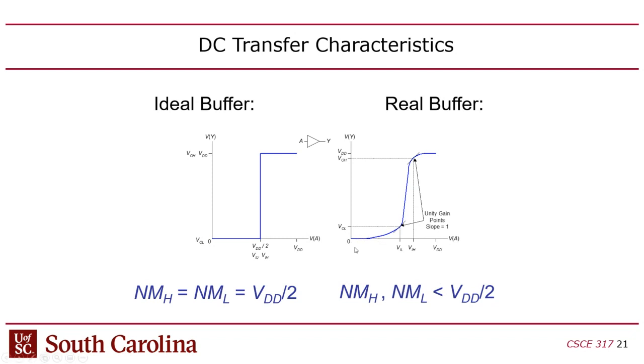So when you have a gate, and I'm not sure if I showed a figure like this, this is a buffer basically. This is kind of like an inverter, but it doesn't invert. You have two plots here. If you look at the one on the left, the horizontal axis is the voltage of A, the input, and the vertical axis is the voltage of Y, the output. So we're plotting the input to the output voltage. Actually, this is the same setup we used when I was talking about the different operating modes of the pull up and the pull down transistors in an inverter. So this is the voltage response of a gate, right?